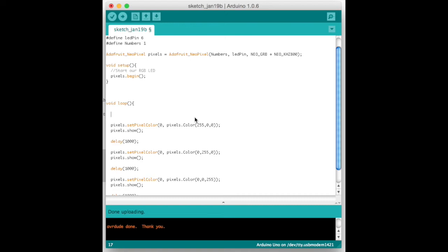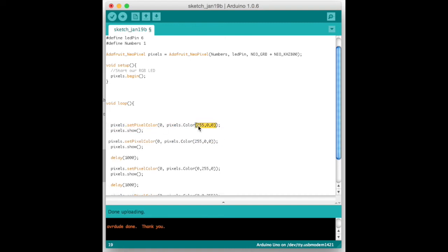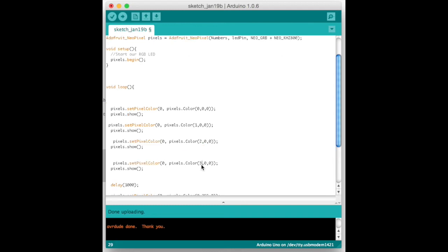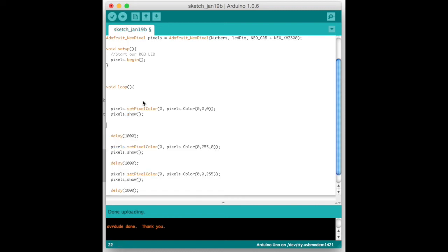But imagine if you have to do this every time, one by one, for example, starting at 0, and then 1, and then 2, and then 3, and so on. This way, the color red is going from 0, which means turned off, until 255 with full power. But that's going to be a lot of work. So in order to do that, we're going to use something called a for loop, which will increase the brightness of the LED without you having to rewrite this function many times.